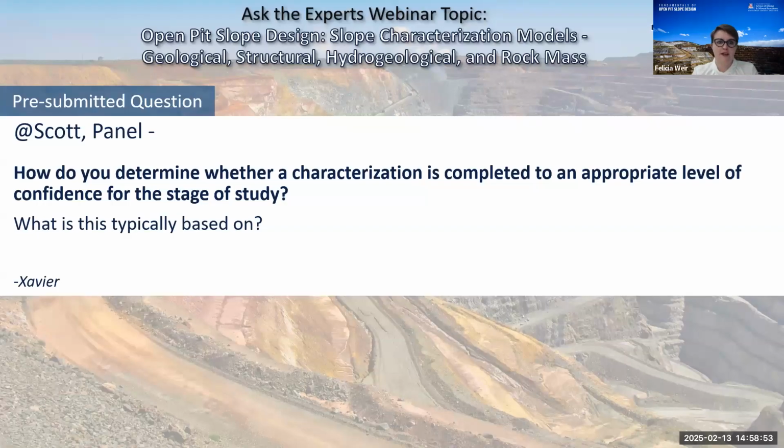Have you got a small starter pit that will give you experience in the slopes, versus are you mining ultimate slopes straight away? That's a very different risk profile, and you likely need a lot more data if you're going straight to ultimate. Yeah, that's a good point, Felicia, as well. How much experience do you have in that particular setting? And benchmarking with other operations, you can get a lot from that also.